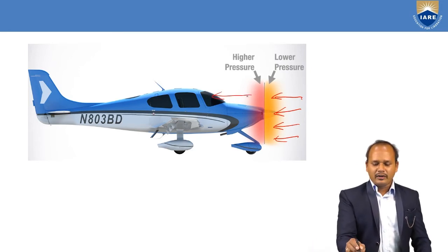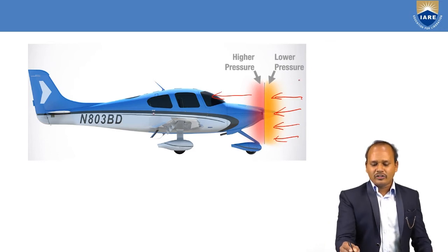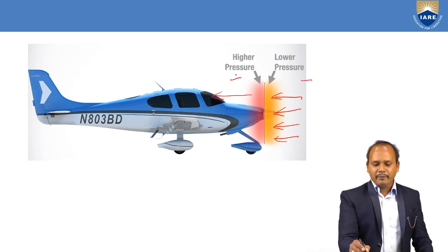So here, from a velocity point of view, at the exit of your propeller, the velocity will be more. As such, we are gaining momentum when the flow is passing through the propeller. At the same time, after some time, that accelerated flow is going to come to rest, that is, it will attain equilibrium with the surrounding. Because of the deceleration, the pressure behind your propeller is going to be increased. So we have a low pressure here and high pressure here.